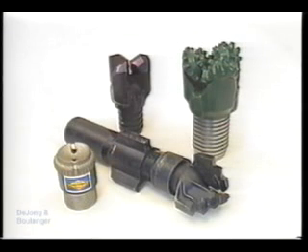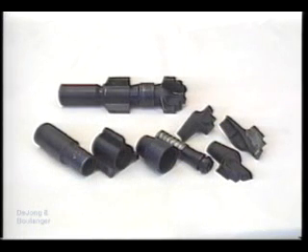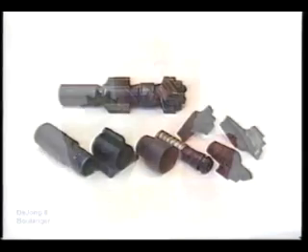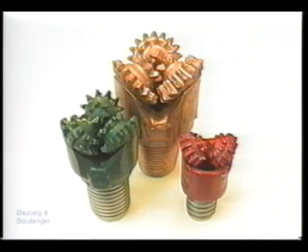Common rotary bits include drag bits, roller bits, and plug bits. The replaceable drag bit, one of the most common, consists of a barrel, bowl, blades, and connectors. This design is economical since worn teeth can be replaced rather than replacing the entire bit. The cone bit has teeth on the surfaces of cones, which rotate as the bit is turned. The spacing and size of the teeth on the cone depend on the type of material to be drilled.